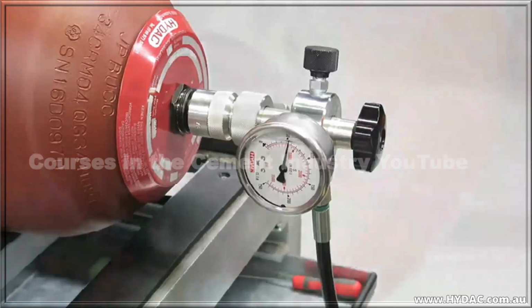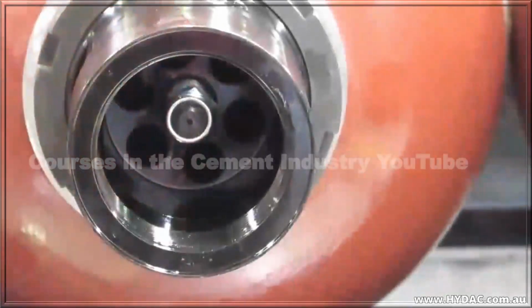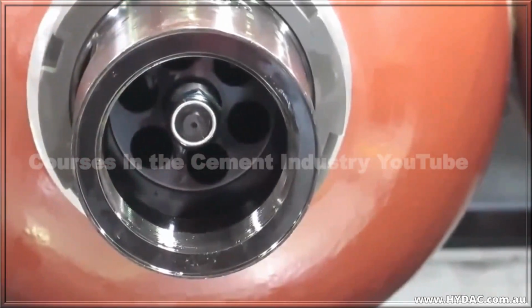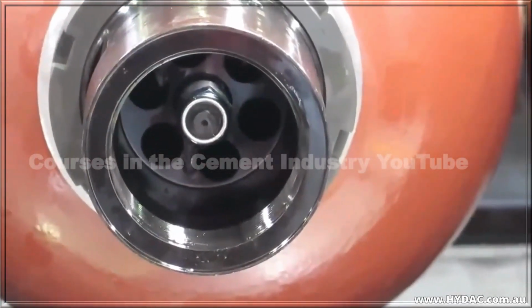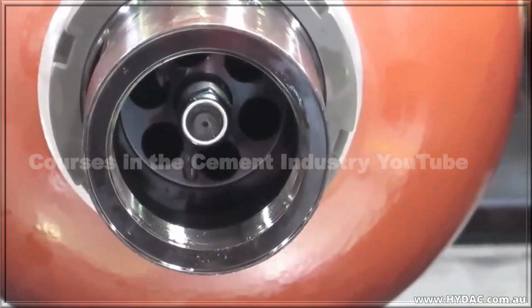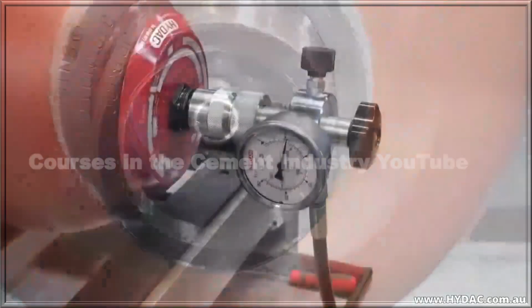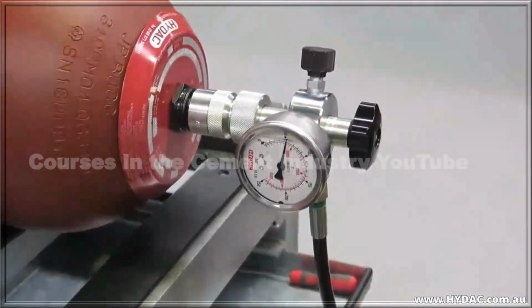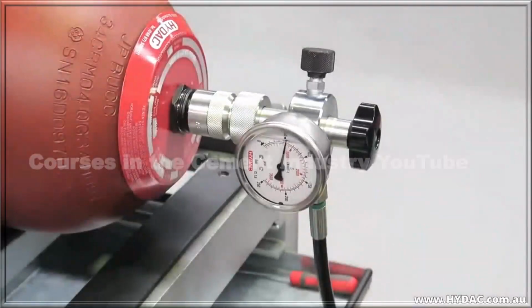You can assess whether the bladder has been inflated through checking the position of the fluid port poppet stem. If it has extended, the inflated bladder is pushing the poppet valve closed. The rate of nitrogen flow may be increased only once the bladder has been properly inflated. Raise the gas pressure in the vessel to the desired pre-charge pressure.